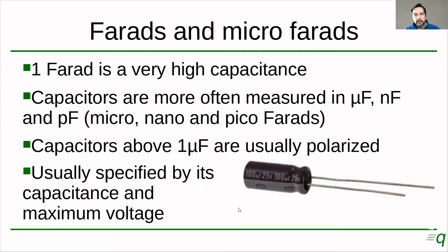Also keep in mind that when you have a polarized capacitor like this one, you have to use it with this polarity. You have to ensure that this terminal has a higher voltage compared to this one. If you reverse the polarity, you can damage the capacitor even if we have a much lower voltage than 25 volts.